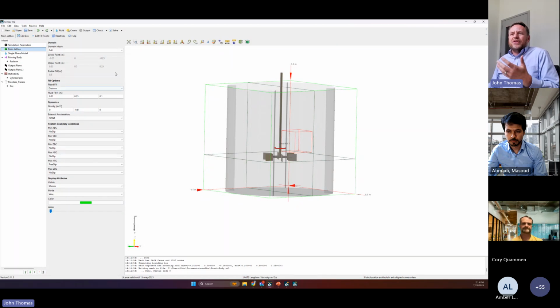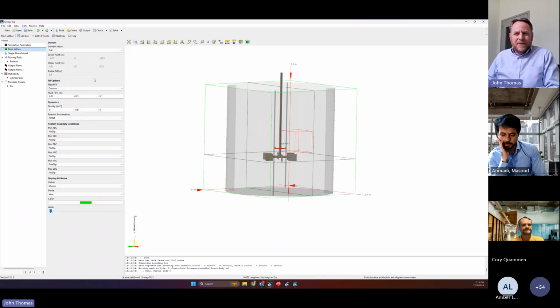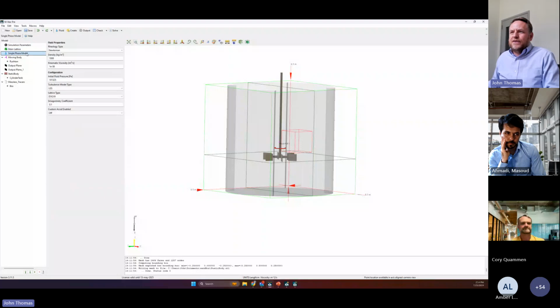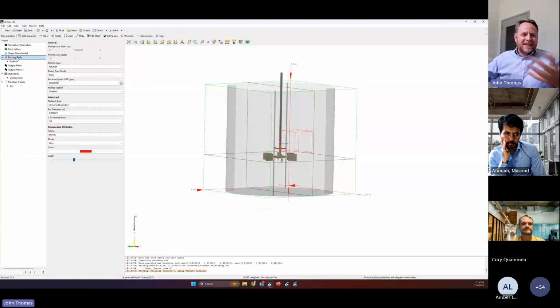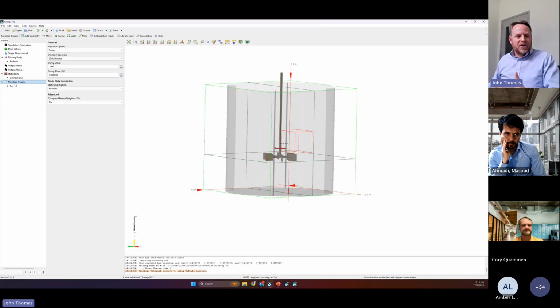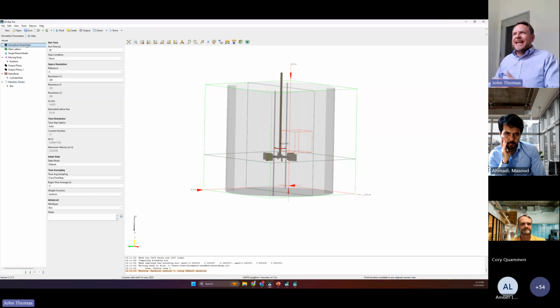But there is some thought. There are still a lot of parameters here, just empirically. I've got to specify rheologies of course, and choose my turbulence model, LES versus DNS. There are still some executive decisions that have to be made. There aren't a lot of decisions, but there's still engineering and numerics that goes into building this model that a chemist may not want to know, understand, or care about. Does a chemist really care whether you're using implicit large eddy simulation or large eddy simulation? They kind of do, but not necessarily. That's more of a decision for the CFD engineer, the numerics guy.